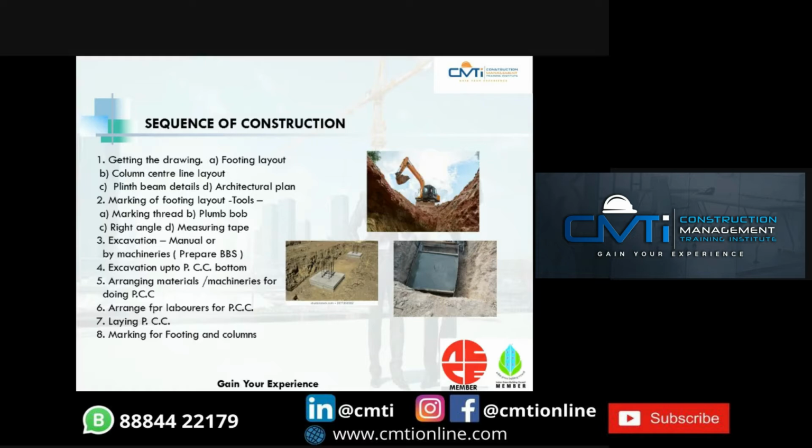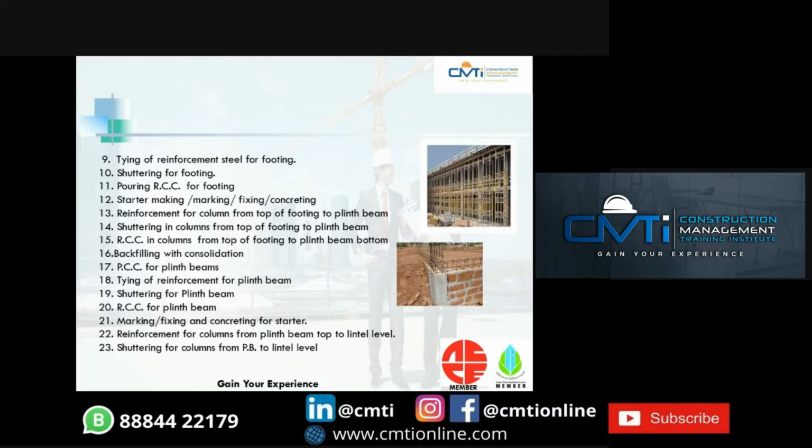Third one is the excavation, manual or by machineries, and then we have to prepare the BBS. Fourth one is excavation up to PCC bottom, and then further arranging the materials and machineries which are going to be used for PCC, then arrange for the labors for PCC, and further laying PCC, and then the marking for footing and columns, and then the tying of reinforcement steel for footing and the shuttering for footings.